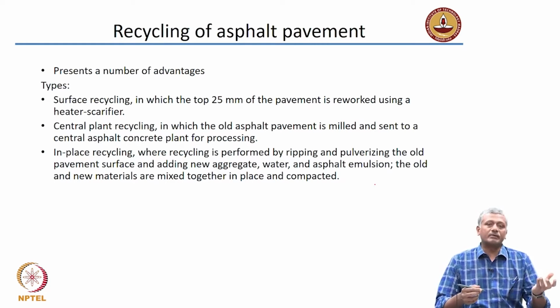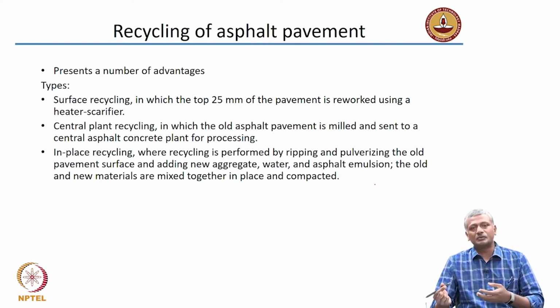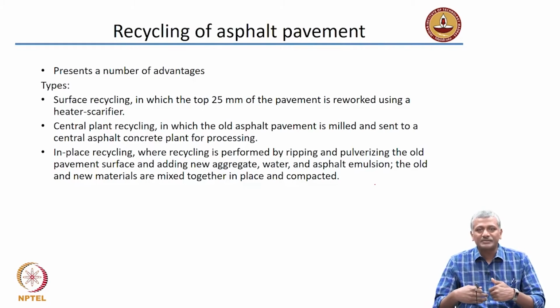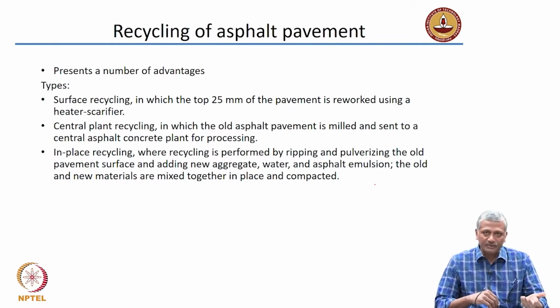You cannot do this with concrete, of course, because once the cement is reacted with water and hardens, you can't retrieve the cement back from it. Asphalt, on the other hand, as I said, does not undergo a chemical reaction to the aggregate. All it does is increase its stiffness or increase its viscosity to have a very solid like structure. Okay. So, in this case, all you need to do is just heat it up to cause it to start flowing again. Okay. So, you can have different types of asphalt recycling.